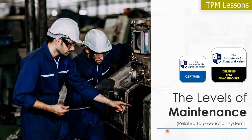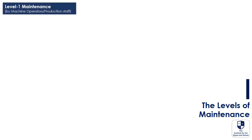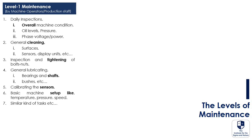Now we will discuss the levels of maintenance. When it comes to level 1 maintenance, these are mainly done by the machine operators or the production staff. This means daily inspections, general cleaning, inspecting and tightening the bolts and nuts, general lubricating, and things like this. By now, we already know about these tasks.